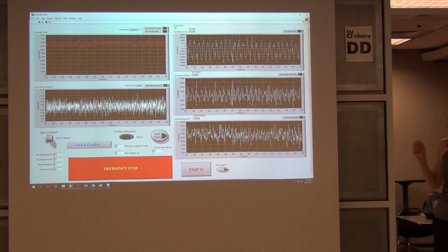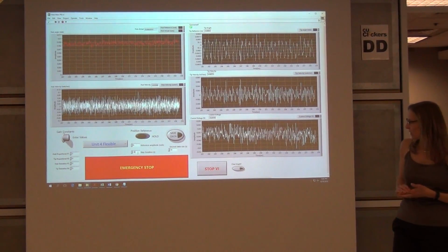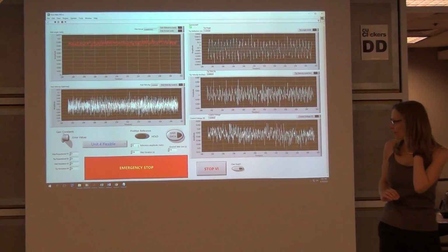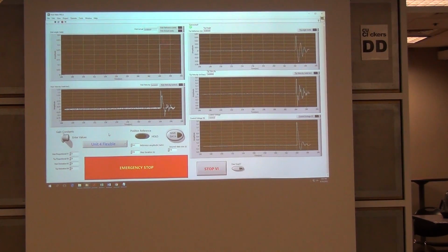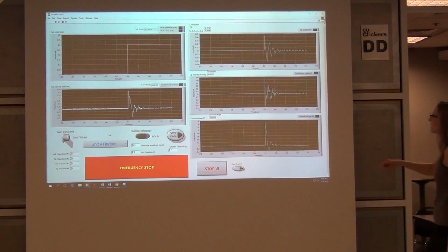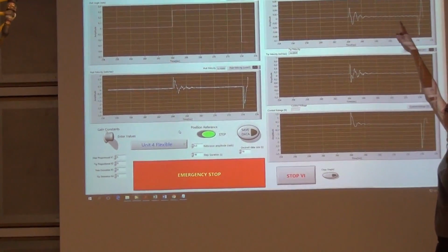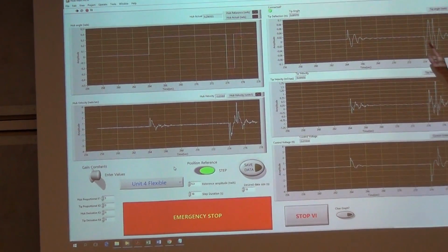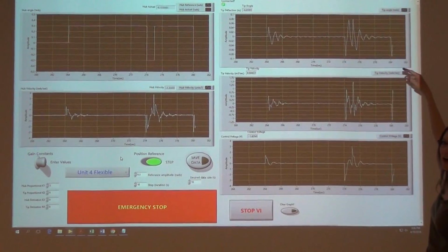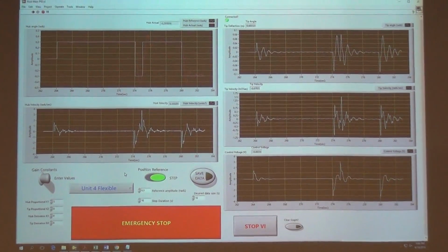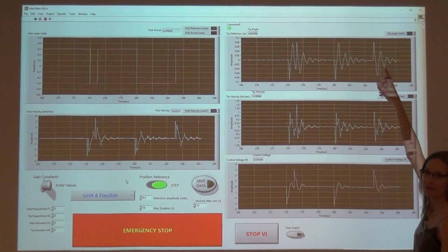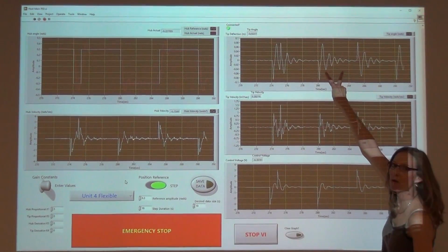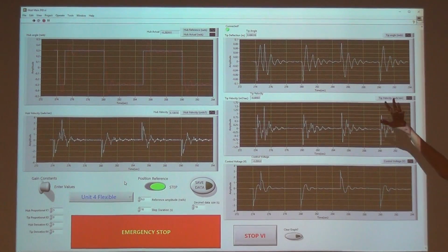Now let's do a step response of just 0.3, and we'll just do proportional. So you can see how bad it oscillates. Without any feedback control, you can see that this system is clearly not critically damped. It goes to where it's trying to go, and then it oscillates, and then eventually damps out. So this is the natural damping ratio of the system. That's how long it takes for it to damp out without any control system added.